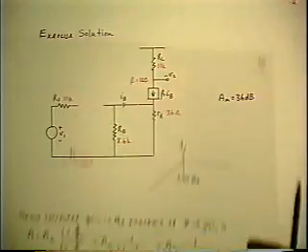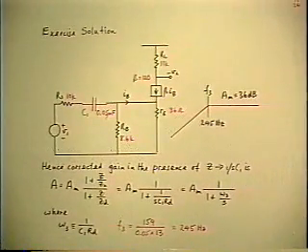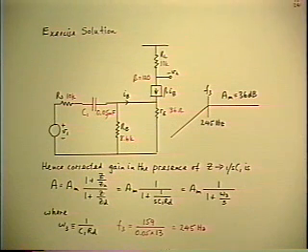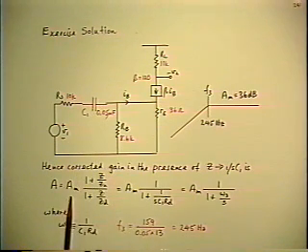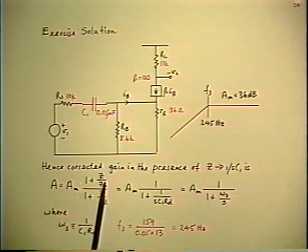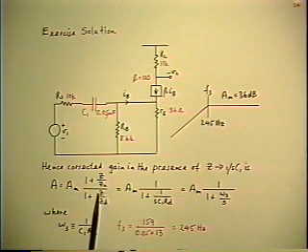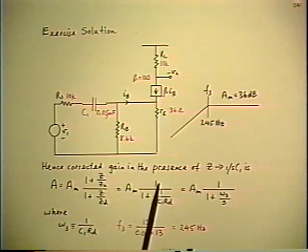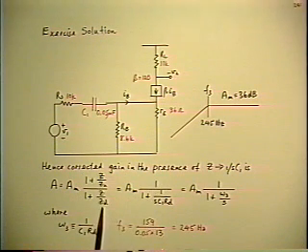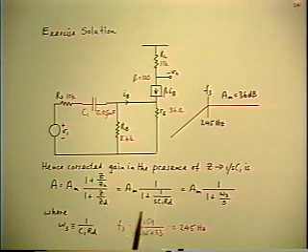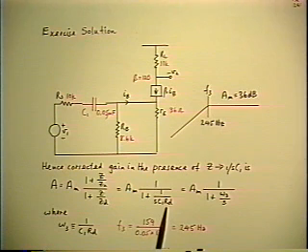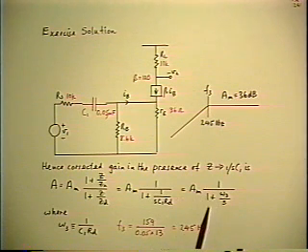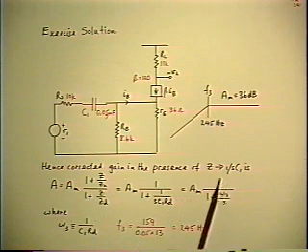And the last step is to put the extra element in there, which is a capacitor. And the series form of the theorem says the gain in the presence of the capacitor is the reference gain when it was an AC short, which is AM, multiplied by the series form of the correction factor, in which the Zn is infinite, so the numerator is 1. And in the denominator, Z is 1 over SC1, and ZD is RD, which we calculated. So you get an inverted pole due to the capacitor, and no 0.